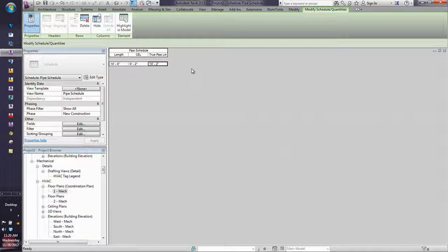We actually did that MCC panel that I brought in earlier. That's an example of how you would do that because you use those yes-no parameters to turn on different segments, different blocks, different regions in there. That's better than trying to just go and use another parameter to control the fill region itself. Yeah, I've tried to do that and it doesn't work because it's actually a nested symbol. Because it's nested, it doesn't work correctly. But if you do it with a yes-no, it works a whole lot better.